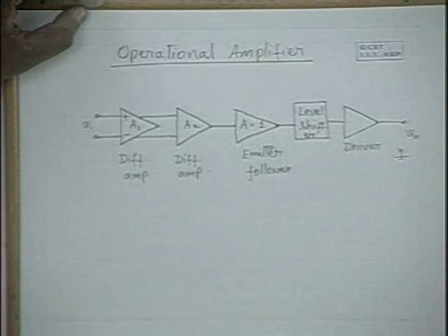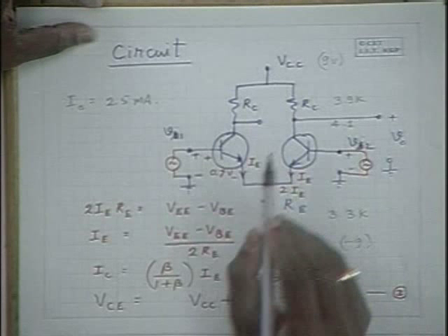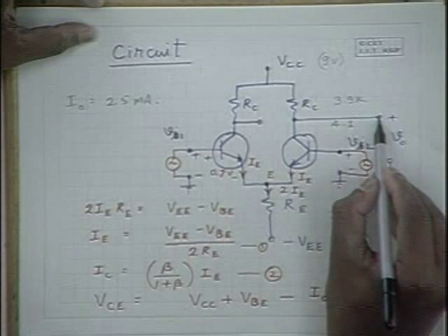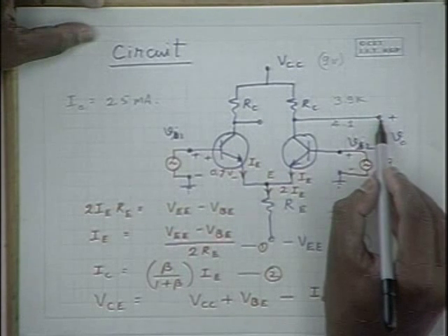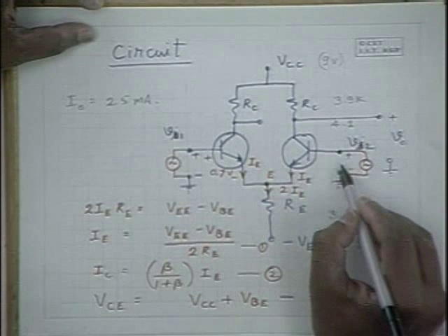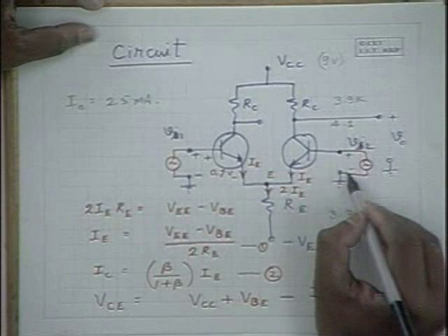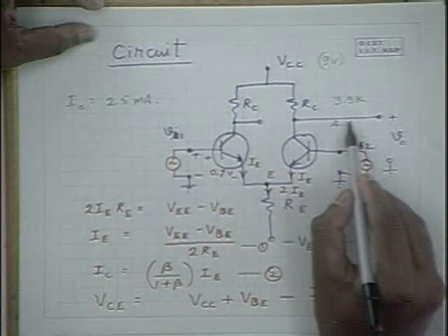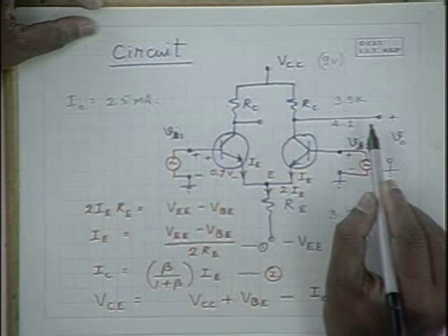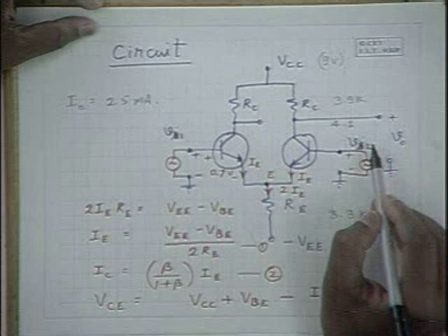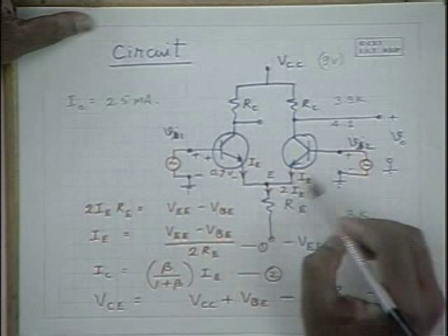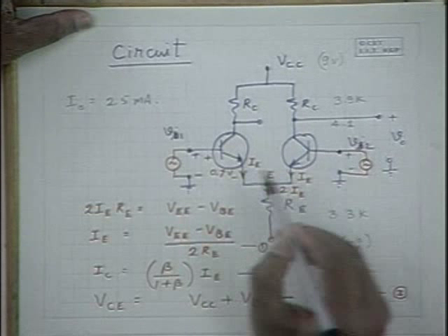And that is possible only when the last stage amplifier is biased around 0 potential. So if you want this circuit itself to operate around 0 potential, the biasing voltage should be 0. Please note that if the base is biased at 0 potential, it's not possible to bias the collector at 0 potential, because it goes into saturation, and the saturation region is not suitable for amplification.